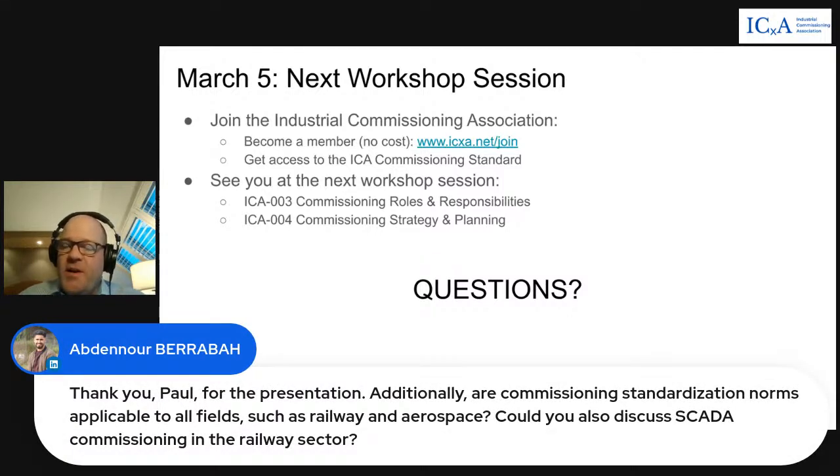Additionally, are commissioning standardization norms applicable to all fields such as railway and aerospace? Could you also discuss SCADA commissioning in the railway sector? Yep. So regardless of what SCADA is connected to, if you're controlling a oil and gas facility, you're controlling a high power system, you're controlling a railway section, it's the same process, right? It's the same PLC based control and protection systems that are managing different aspects of the system. So the steps are very much similar.